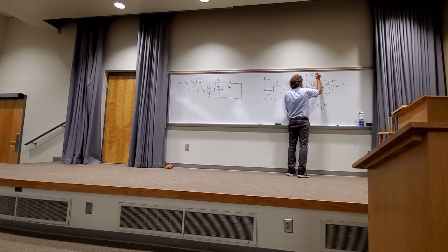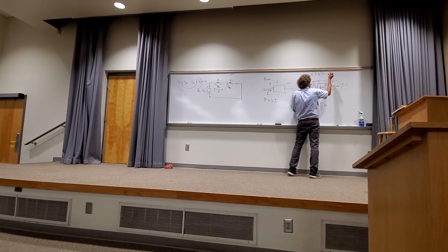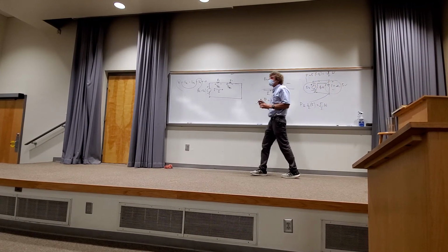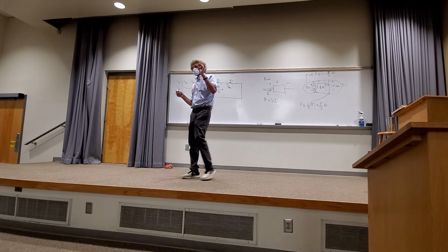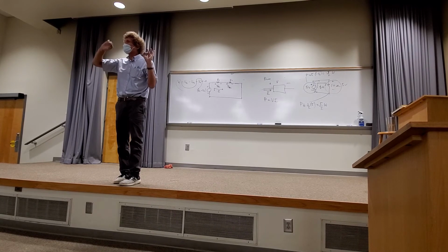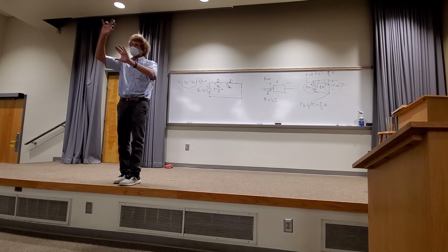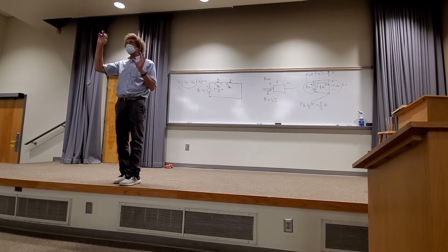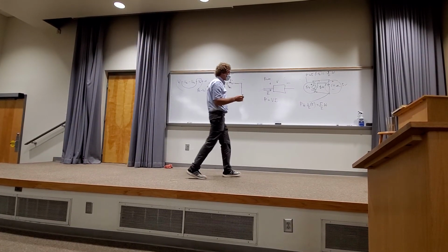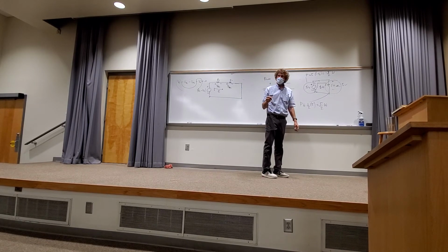So it's times minus 1/2. That's the current. And that means it's going to be minus 5 watts. And the sum of the two is equal to 0, isn't it? Now that's an old way of checking things. If you go around and you've got multiple sources, multiple resistances, if you take the power associated with each element and add them up, it will come out to be 0 if you've done everything right. And if it doesn't, you've done something wrong.